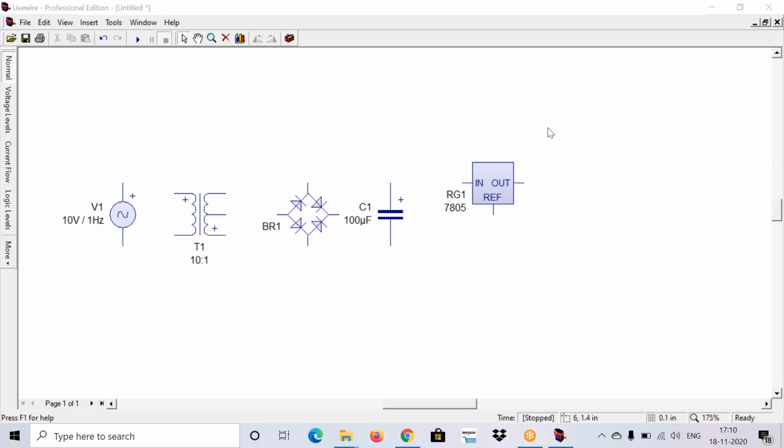Observe the voltage regulator here. It is a 7805 voltage regulator, right? This is a regulator of 5 volts, because if you observe the series, 78 is the series of the regulator and 05 is the output voltage. 05 is the rated output voltage of this regulator. You can identify the voltage levels of voltage regulators like this: 78 is the series and 05 is the output voltage.